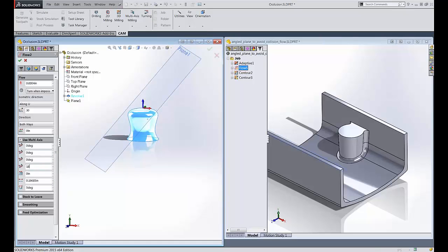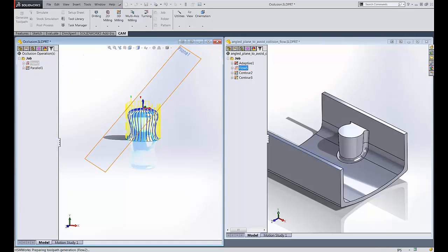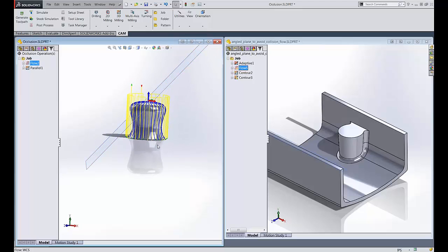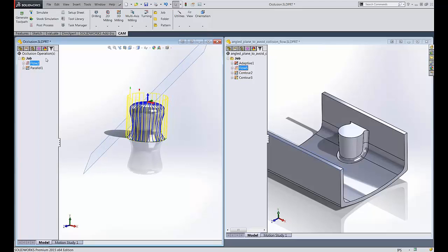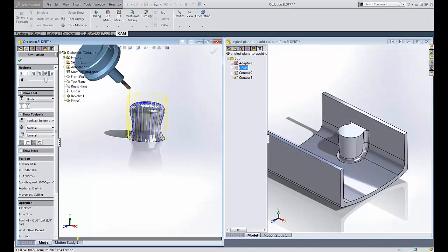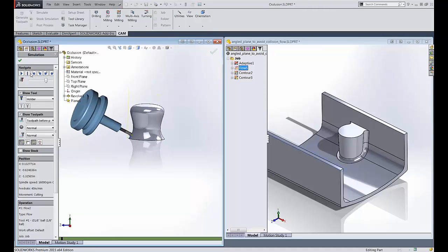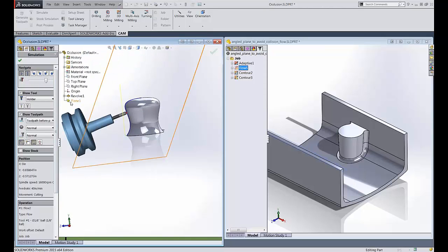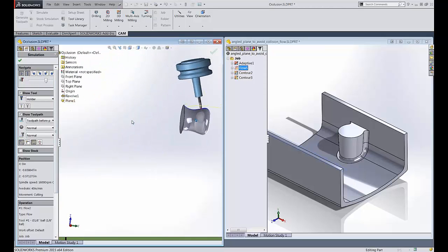So we'll just open this all the way up, and we'll allow it to go negative. And we'll probably actually get some really crazy, oh, we didn't, okay. Sometimes you'll get some crazy stay-down linking moves that want to go underneath. It's funny to me that the default is 180 degrees on multi-axis flow because there's like no applications for that. But you can see right there, this tool is pointed massively negative. In this case, I guess it might be okay.